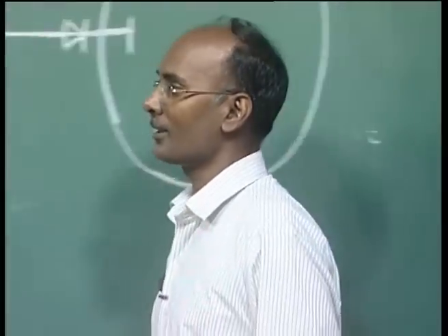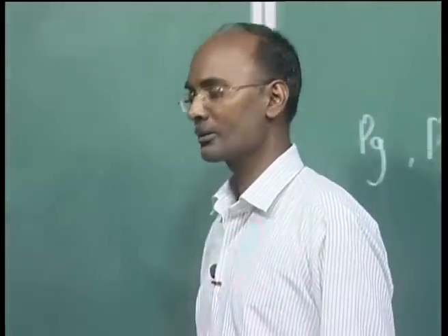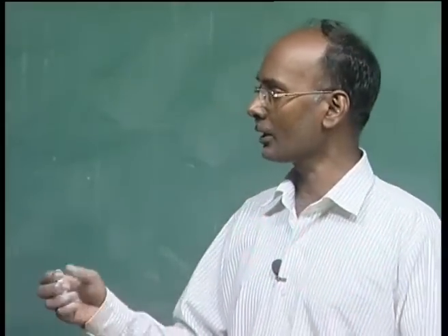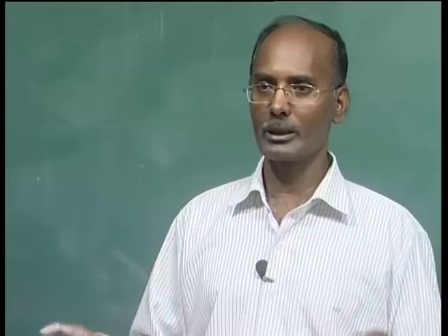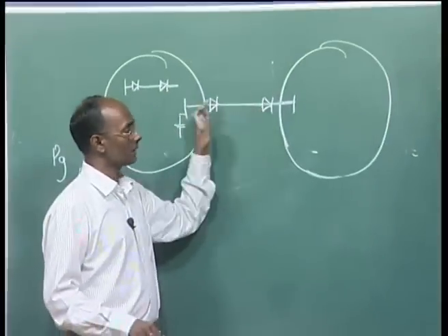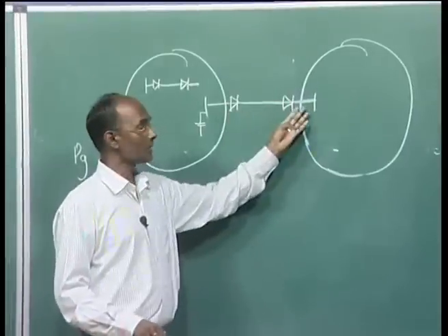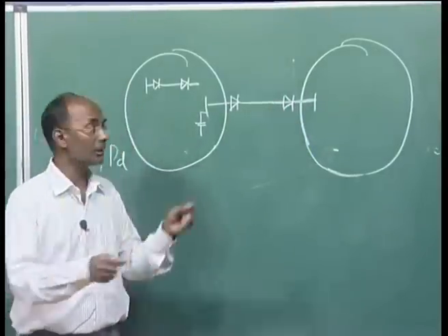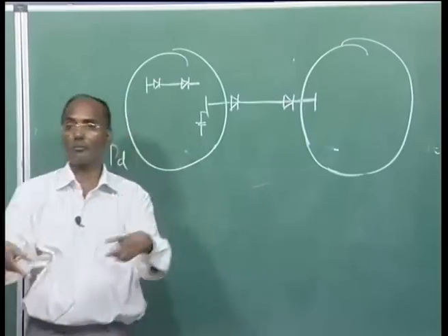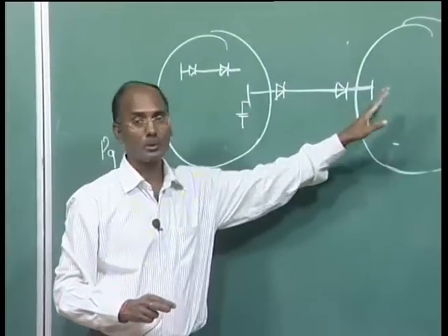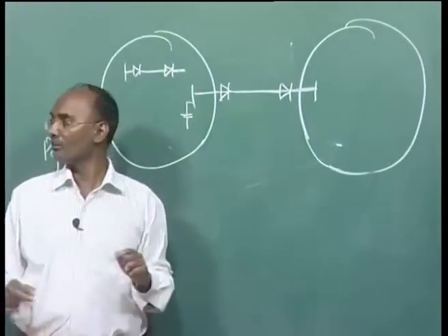So the next control possible is the tie line power control. That is very simple and really very useful, especially when we are talking about back-to-back control. Basically, this is nothing but two areas. Here again we have the HVDC link. It may be a long distance transmission HVDC line, or it may be short distance, that is the back-to-back connection, meaning both converter and inverter stations are very near to each other, and our only intention is to control power from one region to another region, then it is possible.